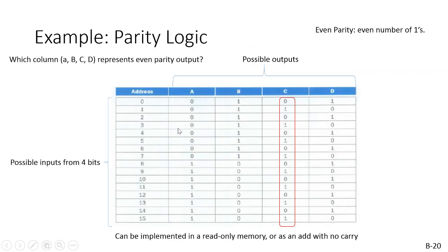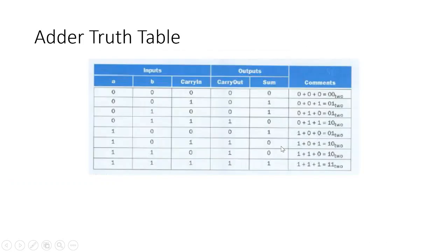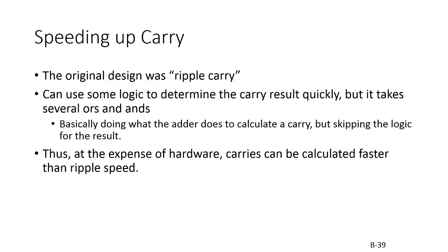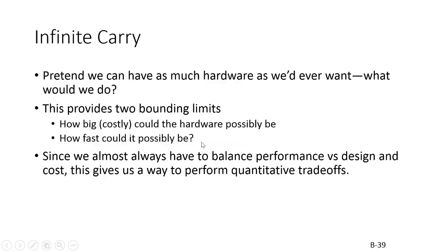We also filled in some of the specifics on VHDL and Verilog, and on explaining synonymous terms here: blocking, non-blocking, or in other words, data dependent and or asynchronous or simultaneous occurring operations. We touched on an adder again to explain what a ripple adder is versus a carry look-ahead adder. So it adds this unit, so things can be done simultaneous.